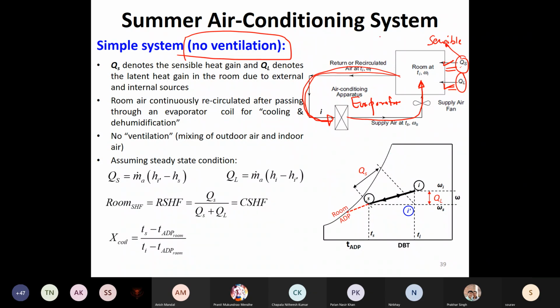So through radiation the walls get heated up, and then it starts to conduct, and then through convection inside the room you will have the heat getting inside. Okay, then you, human, sitting inside doing any activity, will also be releasing heat, both in form of sensible as well as latent. So you will perspire, that perspiration will increase the moisture content inside.